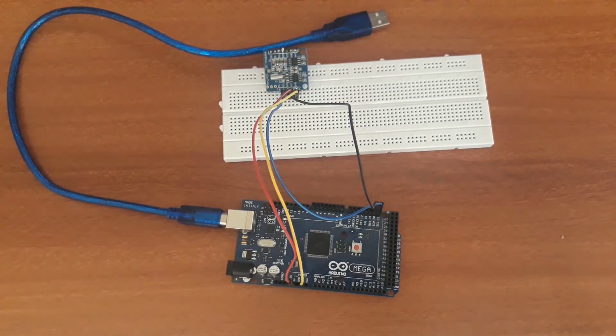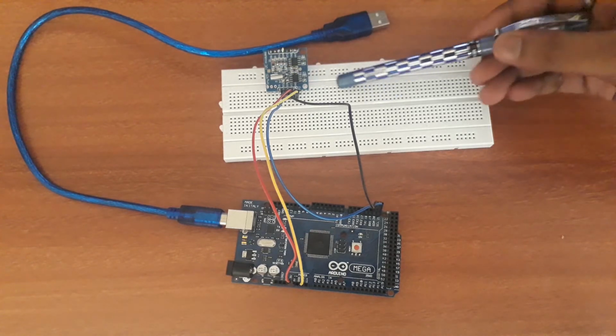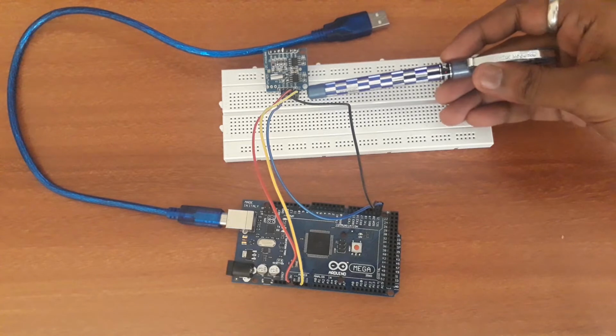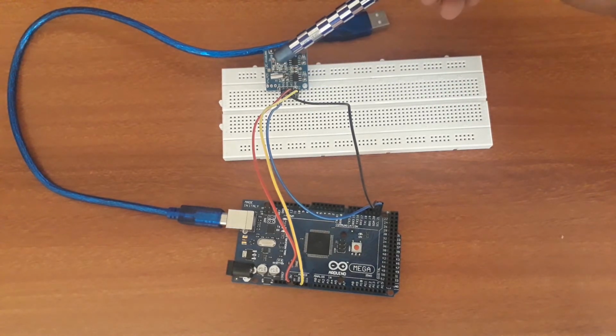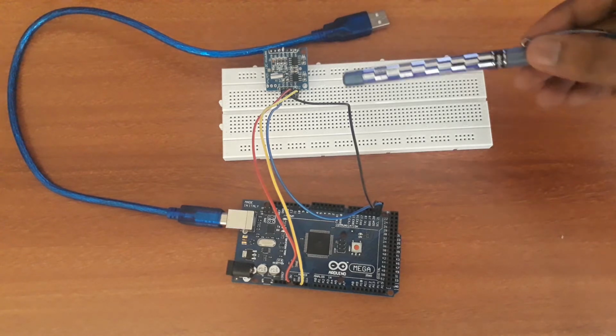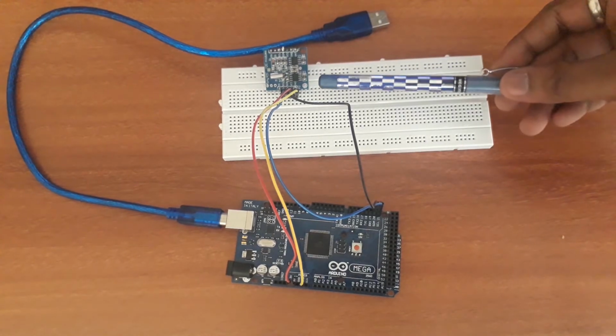Okay, now let's take the circuit, how it's placed. Now already I explained regarding the RTC. Total RTC 4 pins are there. The first pin on the right hand side we can say it is a ground. After that positive VCC, then SDA, and the last one is SCL. Then whatever I explained in the circuit diagram in our PPT, the same manner I connected.